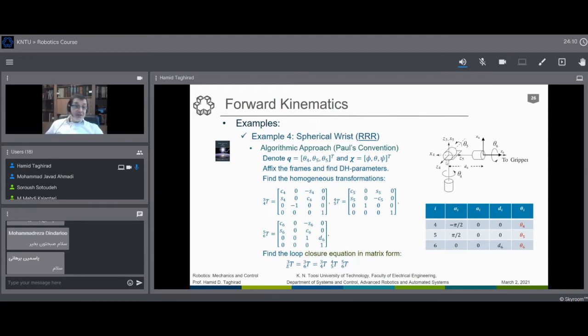Of course, as I mentioned, these are not unique. You can have some freedom of choice here to select some particular cases. Of course, not the z-axes. The z-axes are all assigned by the direction of rotation that we have here. But the x-axis could be, instead of being this way, in the other way. But if assigned in this way, then we can find the Denavit-Hartenberg parameters. Let me go a bit slower here, as another example to find the parameters.